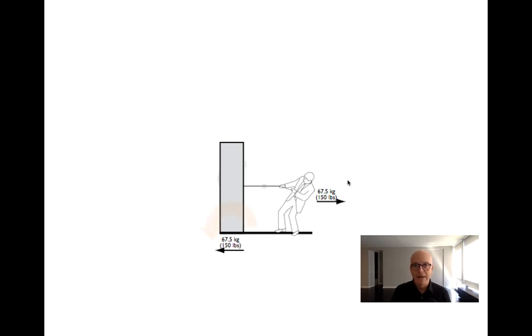Now, just to give away the ending here, what happens is that the wall, hopefully, is so heavy that it imparts its own resisting moment, right? It has a very, very heavy weight, and it too has a moment arm, which is the distance between the center of gravity and the point at which it wants to be a fulcrum, right, or an axle. So here, there's a point right here at the corner of the wall. There's the weight of the wall acting through its midpoint, and it will have a very, very short lever arm, but an awful lot of weight. And at least to a certain point, that resisting moment will mean that the wall not only stays in translational equilibrium, which we get from here, but it will also stay in rotational equilibrium, right? It won't fall over.